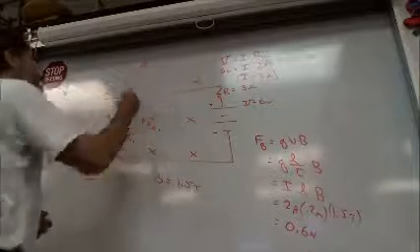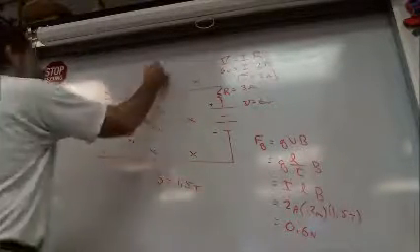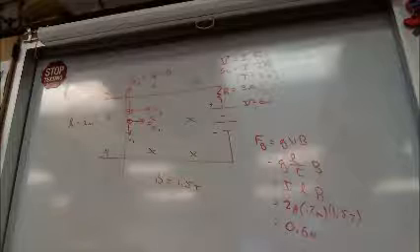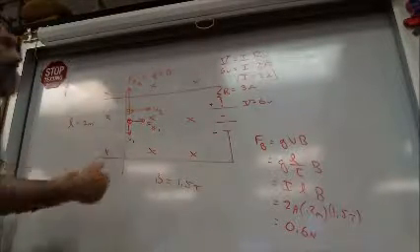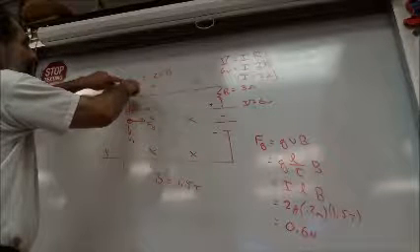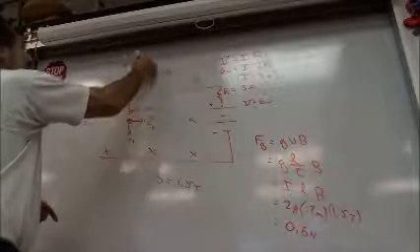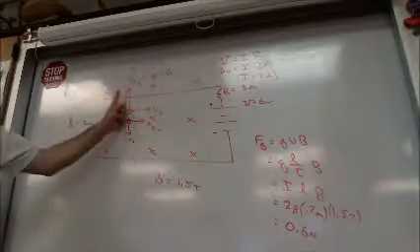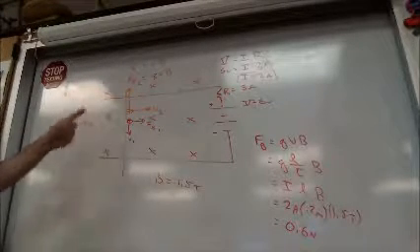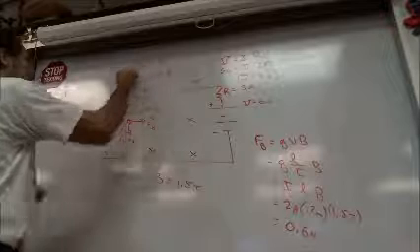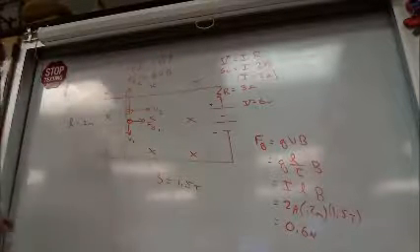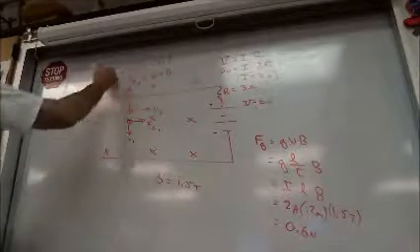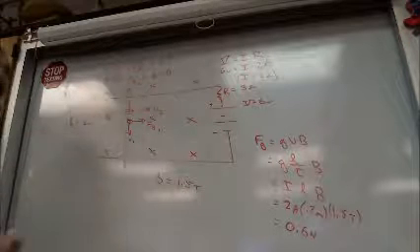Does anybody know the formula for the magnetic force? Q, V, B. Doesn't that sound familiar? Now, just because I've done these many times, I know what I want to do. Could I take that force and divide by the Q and say E equals VB? So there's going to be an electric field the wrong way. And then that electric field, what if I multiplied it by the length? That gives a voltage, and this is called an EMF in these types of problems. That voltage is called a back EMF.